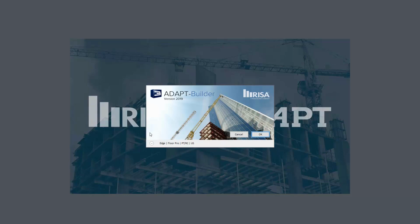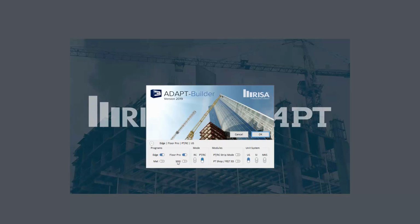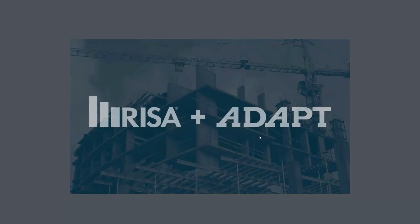Okay, so we'll go ahead now and just open the program. And we're going to use an RC system here for the example. We'll be using Floor Pro. This allows us to model elevated slabs and beams. And we can turn edge off. We'll use US unit system for this example.